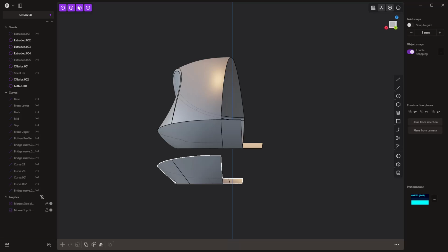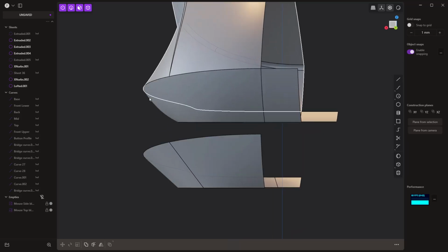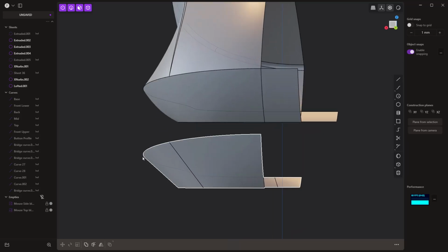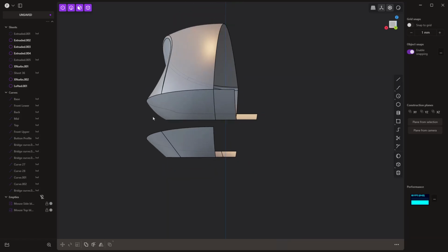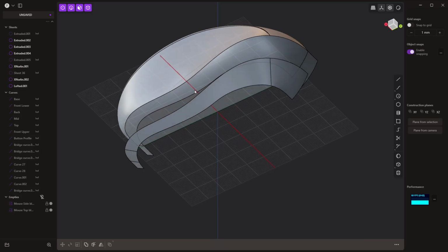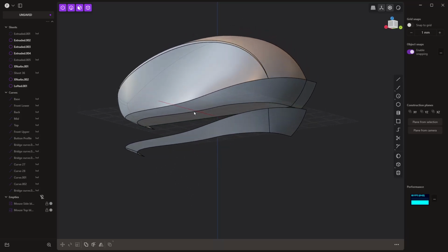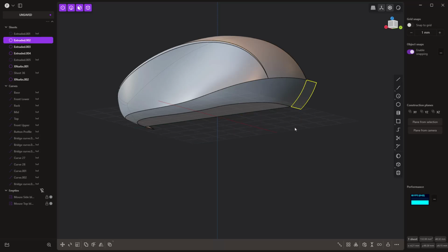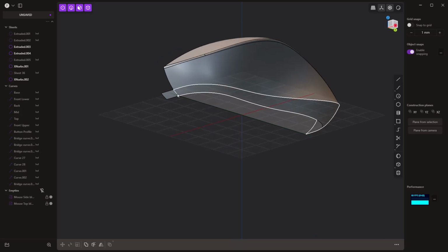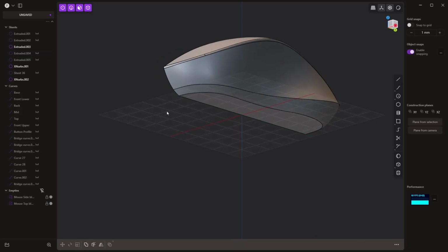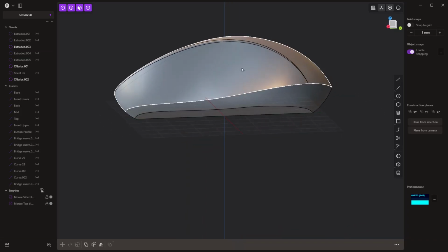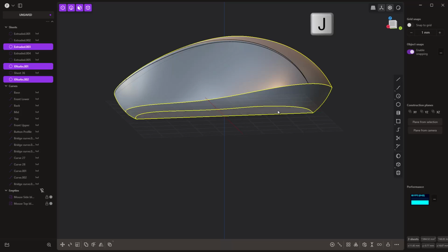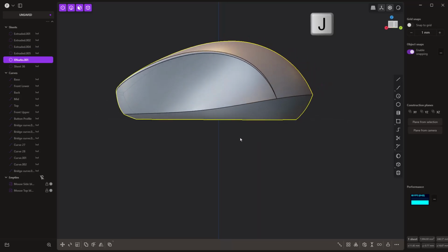So you can kind of see here, the xNurbs surface is rounded where the loft is really just straight from one edge to the other. So it does give you a different result, definitely something that you need to look at, but you could certainly do it with the loft. You could use some intermediate guides and play around with the shape a bit more. But just so we understand that there is a difference in some cases when you're talking about using loft versus xNurbs. Now, select all of these, J to join them together.